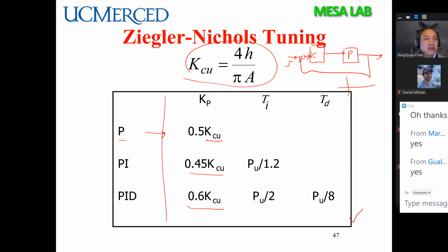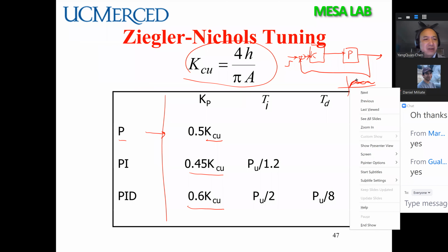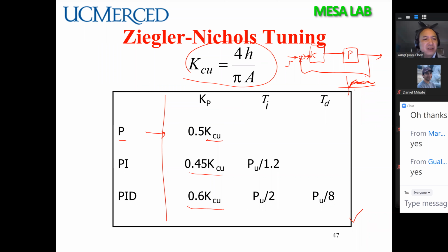Then you have a K, and your system responds like this. You increase the K, your system responds like this. You increase again, you oscillate more. You increase it very big, then your system will be unstable.